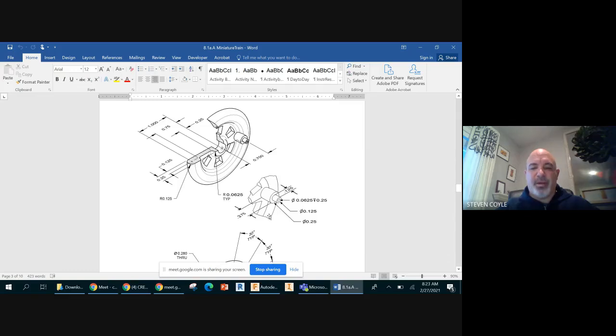But right now we just want to go here. The bigger circle is going to be 1/4 of an inch. And this smaller one here is actually going to be 1/8 of an inch. You're going to extrude it up 0.375 for the first part and 0.125 for here. And these are the dimensions for your hole. It's going to be a diameter of 0.0625 and it's going to go down 0.25.